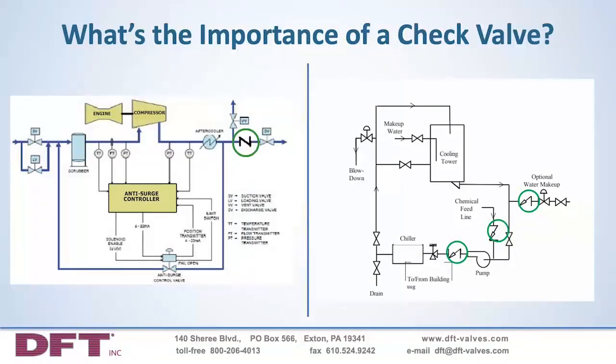Regardless of whether you're using pumps or compressors, they are always a critical power source and a significant investment in your fluid flow systems. Check valves are vital protection to these pumps and compressors, ensuring safe and effective operation by allowing flow in one direction only and preventing flow in the opposite or reverse flow direction.